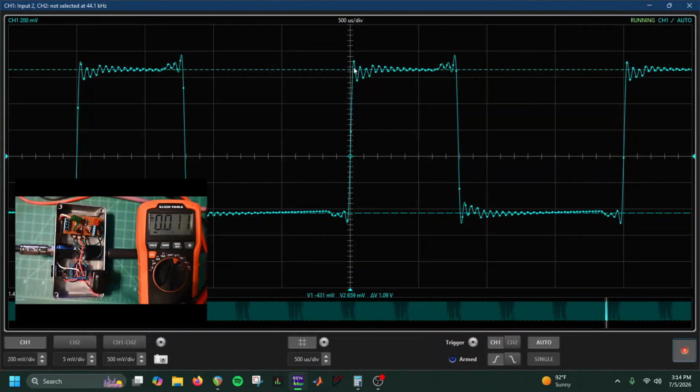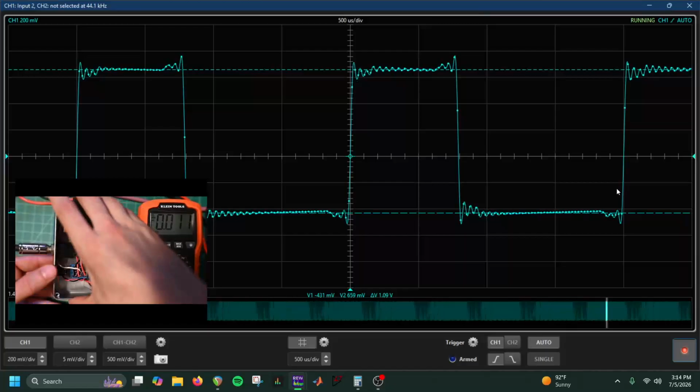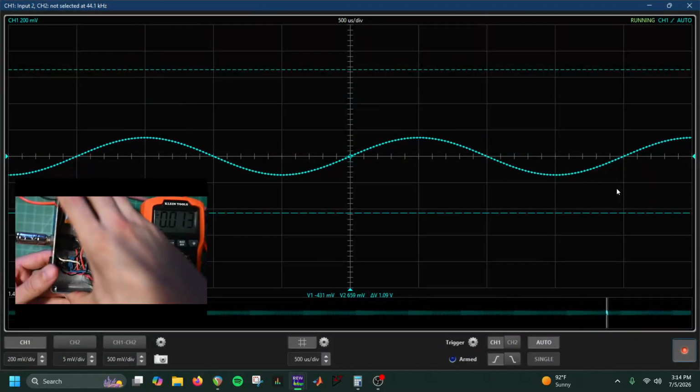The other thing you can see is that the time scaling between these bars is about half a millisecond, so 500 microseconds from here to here. We know we've got a sine wave that has symmetry in the time domain, right? The rise time and fall time in that waveform is the same.